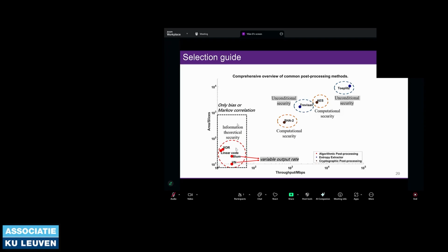When the entropy source is of low quality, entropy loss becomes a critical issue, making proper line code the best algorithmic post-processing method. On the other hand, when the entropy source is of high quality and hardware overhead is a primary concern, VN and XOR should be considered first.